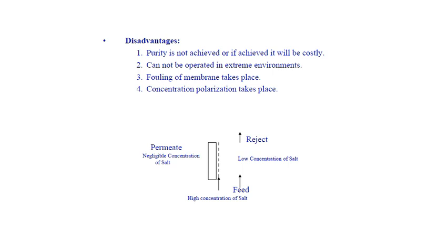So fouling always takes place in the membrane, and you are required to replace the membrane after some time. Generally the time is sufficiently large, like in reverse osmosis you have to replace the reverse osmosis cartridge after 1 year or 2 years. So membranes cannot work infinitely. You have to replace the membranes due to fouling.